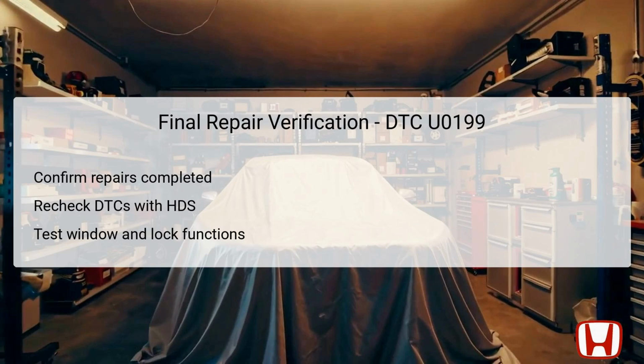After completing any necessary repairs, recheck the DTCs using the Honda Diagnostic System, HDS, to ensure that DTC U0199 does not reappear. Additionally, it is essential to test the functionality of the power windows and door locks to ensure they are operating without issues. Successful completion of these tests would indicate the problem has been effectively resolved. The technician should also document any repairs made, and inform the vehicle owner of the processes involved.